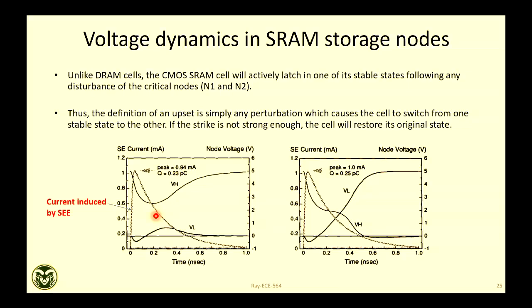So one big message from SRAM you got is that the propagation delay in the inverter matters. Longer propagation delay is better. Suppose you have an SRAM which has a smaller delay, right? You designed it. How do you increase this propagation delay? There are wires.